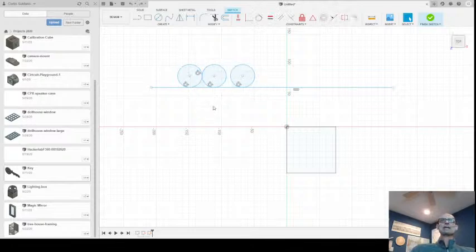So what I'm going to do is I want to constrain this line now. Even though it's horizontal, it can still move up and down, which is kind of messing up my ability to scale these objects. So I'm going to create a coincident between, and I need an actual item. I can't go to just any grid item. I have to actually go to an anchorable item.